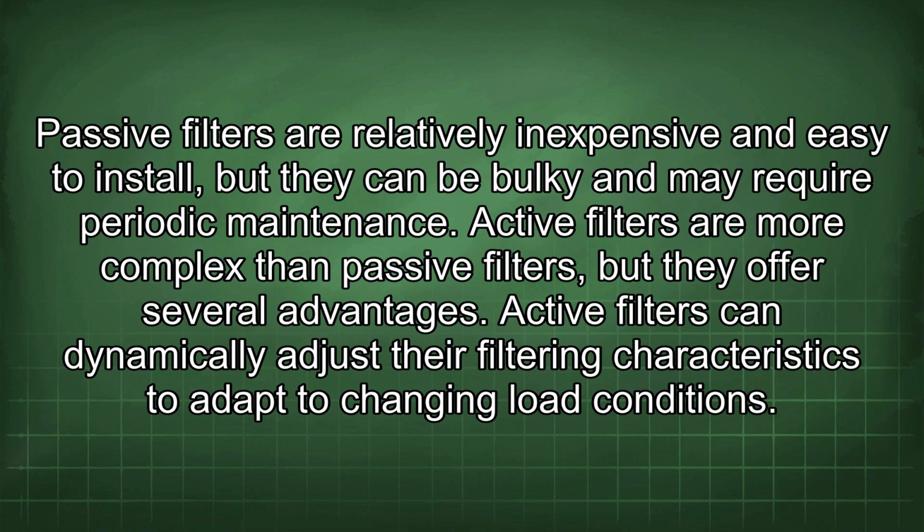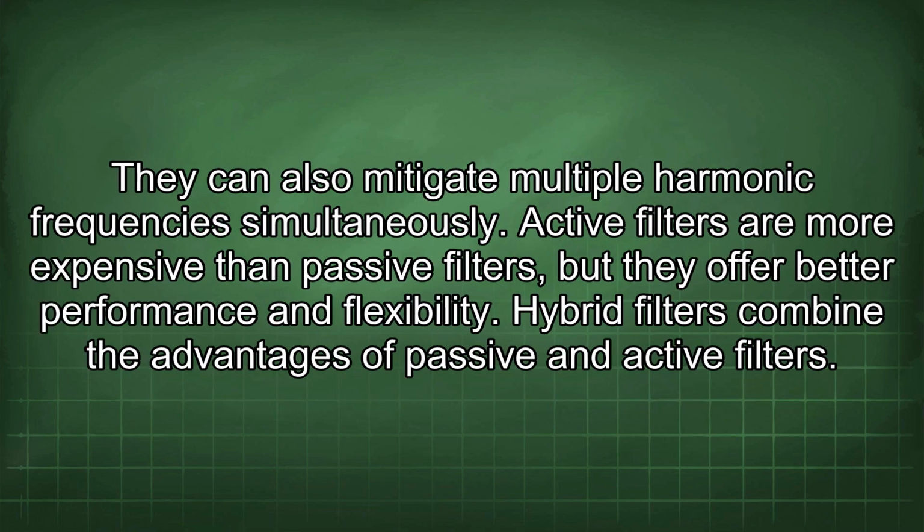Active filters are more complex than passive filters, but they offer several advantages. Active filters can dynamically adjust their filtering characteristics to adapt to changing load conditions. They can also mitigate multiple harmonic frequencies simultaneously. Active filters are more expensive than passive filters, but they offer better performance and flexibility.